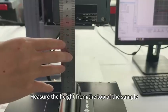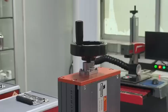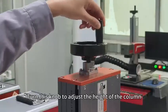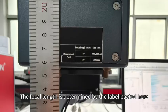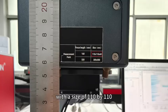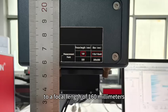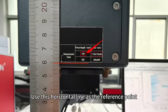Measure the height from the top of the sample to the marked position of the field lens. Turn this knob to adjust the height of the column. This is the focal length. The focal length is determined by the label pasted here. We are currently using a field lens with a size of 110 by 110. 110 by 110 corresponds to a focal length of 160 millimeters. Therefore, the measured height is 160 millimeters. Use this horizontal line as the reference point.